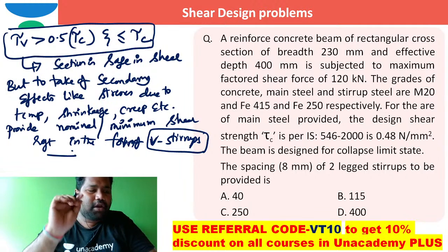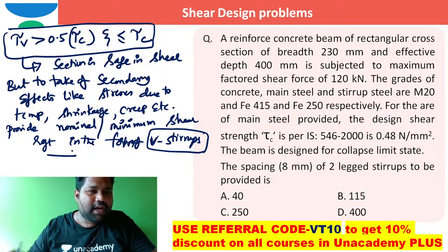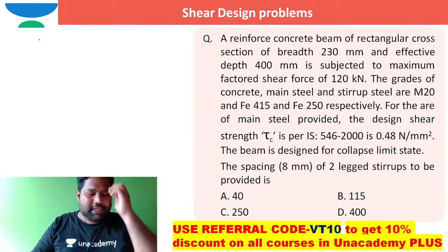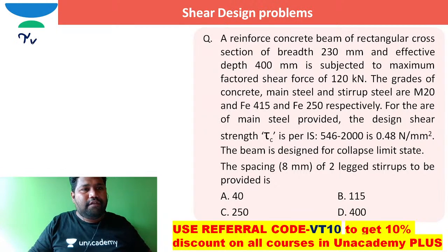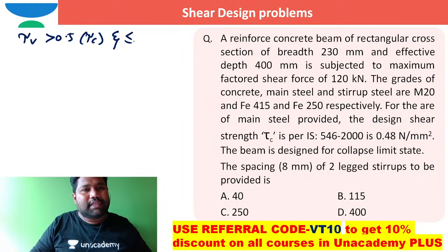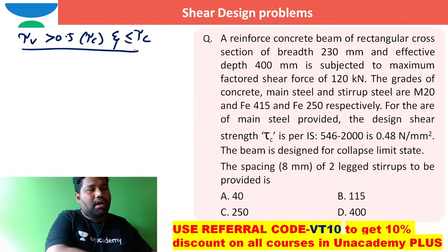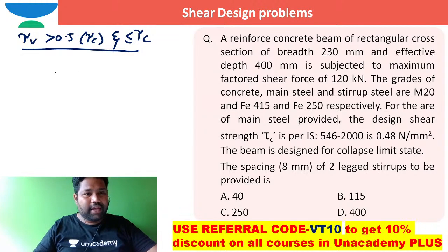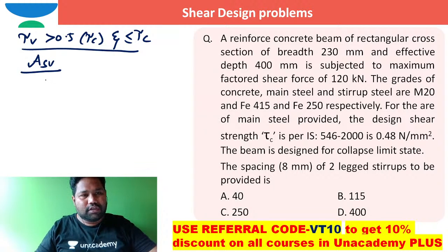I hope you have taken the screenshot till now also. Let me rub the screen. Now the condition is, sir, when tau v is more than 0.5 times tau c and less than or equal to tau c, how do we design this nominal shear reinforcement? Everybody will ask. So coming to this nominal shear reinforcement, we can write Asv. Using this equation, we will design the nominal or minimum shear reinforcement.